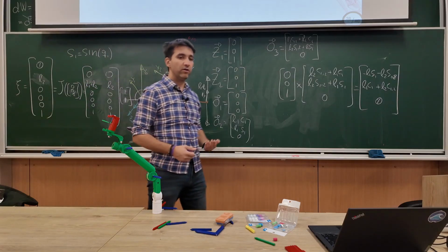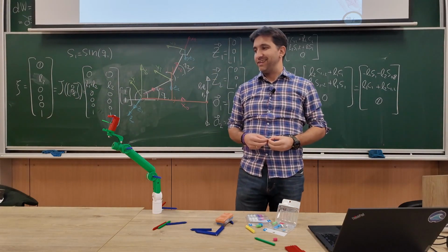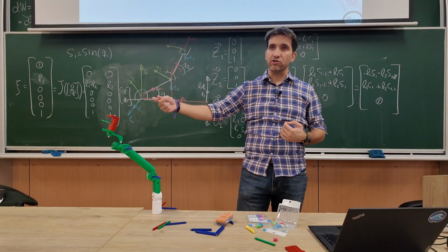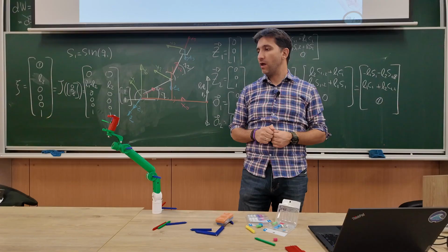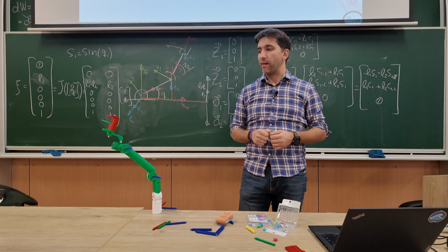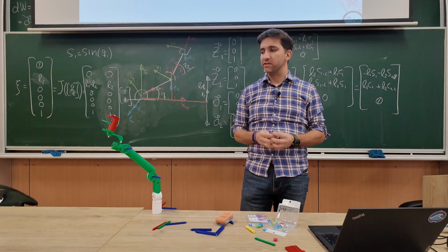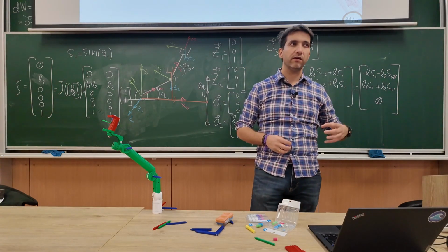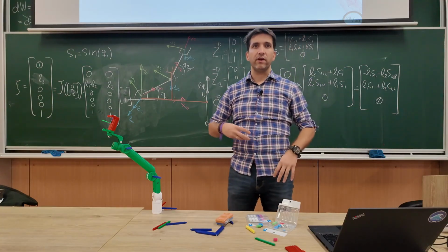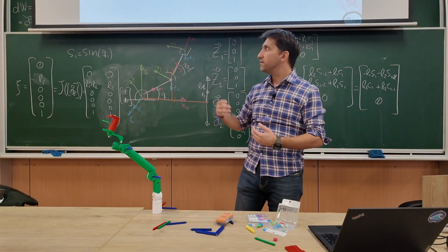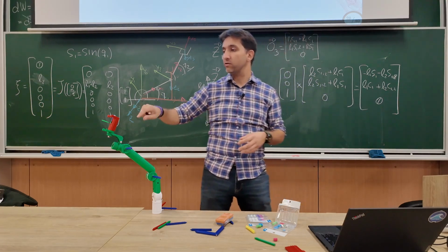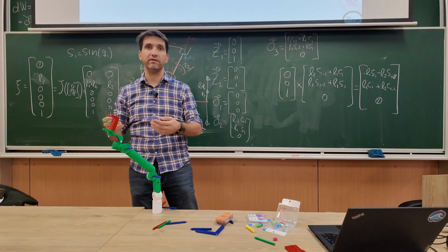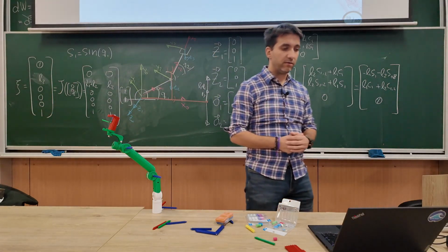Great. So in order to be able to invert this matrix and be able to control the end effector velocities, I need 6 joints. And if you remember our discussion on forward kinematics, the second lecture, we were saying that the number of joints is relating to the number of degrees of freedom. So basically this tells me in order to be able to control the end effector velocity in all 6 directions, so have 6 degrees of freedom, I need 6 joints, right?